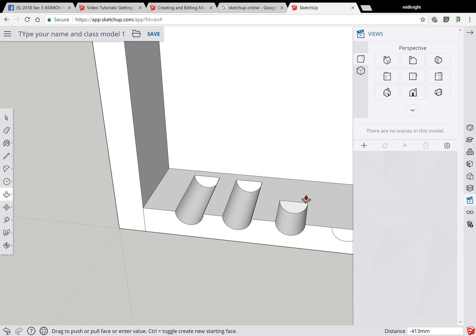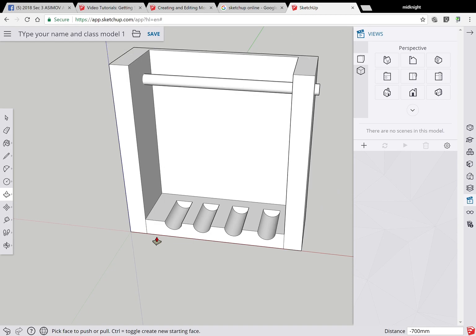By right you need to actually measure the distance. Let me do that again. I'm going to drag and extend it, say maybe 700. Sorry, no. Yeah, 700. I'm going to type 700. Then I go up and type 700 mm again, and again 700 mm, so I get them all the same at 700. Okay, zoom out. So I got that.